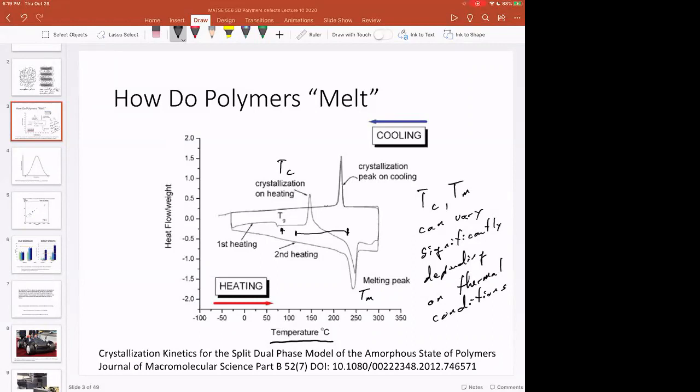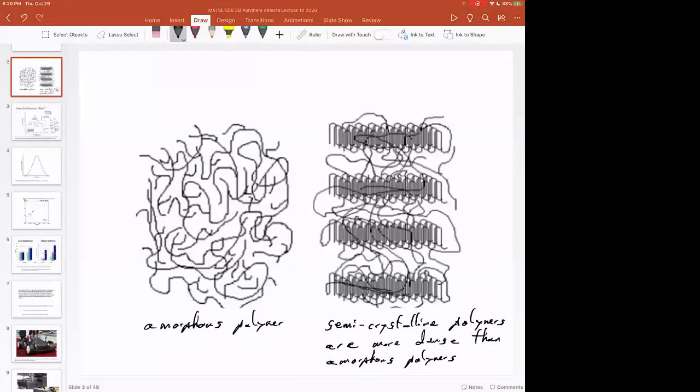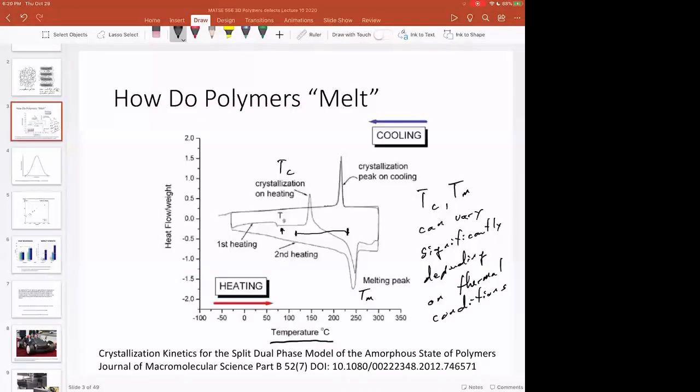And so if you've taken a polymer science class, you know that Tc and Tm can be anywhere between Tg and Tm0, which is the equilibrium melting point. Depending on how long a material is allowed to crystallize, how thick the crystalline lamellae are, that will determine Tc and Tm. So that's sort of in the weeds of polymer physics, but this idea that you can have different crystallization in different places in the part is totally reasonable because of the long thermal transients that we saw in the previous lecture.